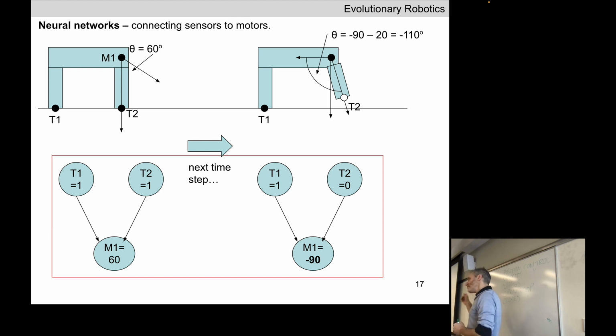So it's good news and bad news for us as roboticists. If we could just program the amplitude and frequency of the leg into the brain, that'd be a few lines of code. We could program it in and off we go. Not so easy to figure out how to design the robot. What should the length of the leg be? What should the mass of the robot be? What should the weights of the synapses be so that we get, for example, some desired oscillation? Maybe we want the front leg to rotate forward and back at about 1 hertz, 1 cycle per second, for example. Not so easy to see how to program the robot to do it.